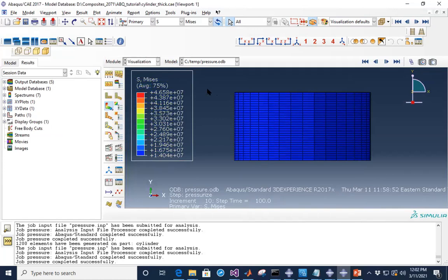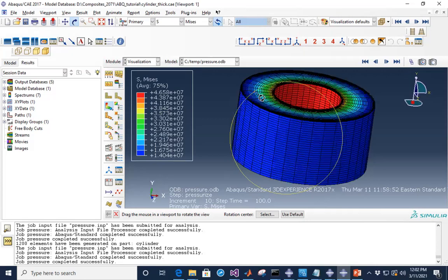So how you can look at that is go to this option right at the top here, and if I hold the cursor over it, it says rotate view. So I'm going to hit that rotate view, and once I do that, the cursor changes to this rotation symbol, and once that is the case, we can click and move our mouse to actually rotate the body.